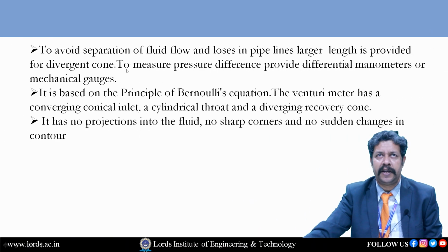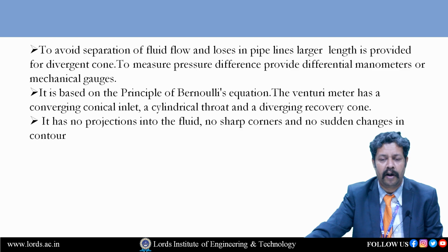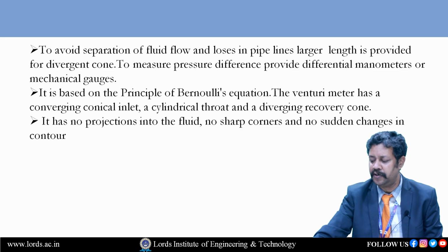To avoid separation of fluid flow, normally a large length is provided for the divergent portion. Differential manometers or mechanical gauges are used to measure the pressure difference between these points. And not only that, this Venturi meter mainly depends upon the principle of Bernoulli's equation. This already I have told you. And in this case, no projections will be there, no sharp corners, no sudden changes in contour are occurring in the case of a Venturi meter.